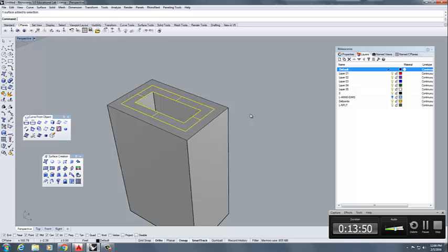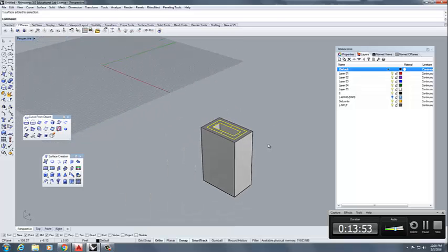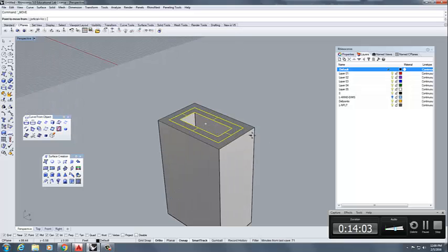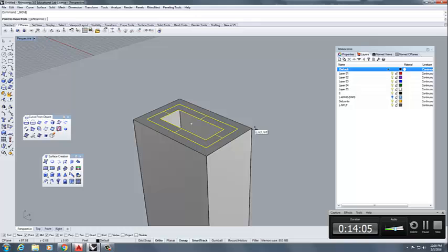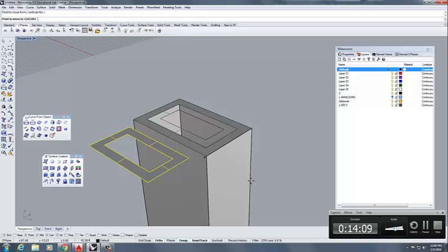And now I'm going to move it down. Now, I want to move it down, so you might think, okay, the construction plane is going to want me to change the construction plane. But as I said before, if you use snaps, you can just move it. So if I type M, and in this case it's saying, where do you want to move it from? I'm going to actually click on the outside corner of this, and I'm going to snap. I need to turn near on, so I can snap near this thing all along this edge.